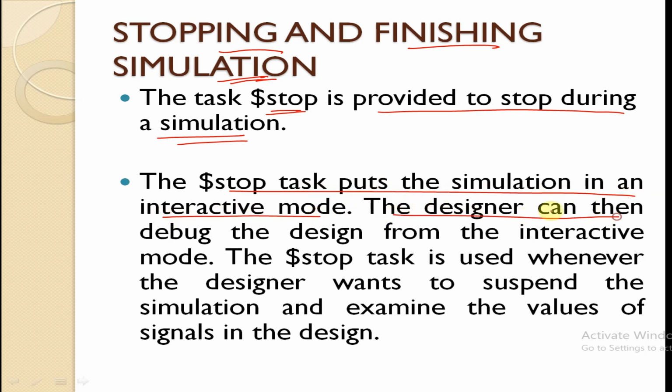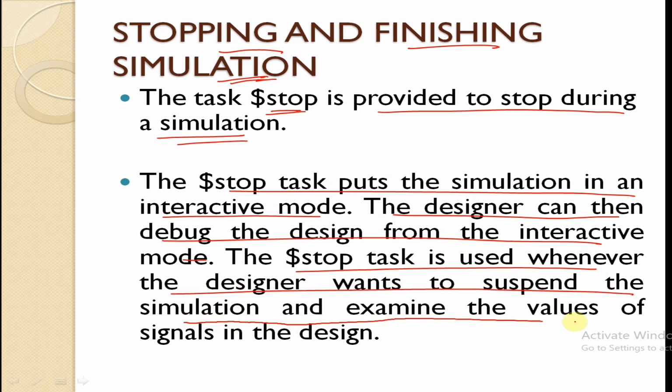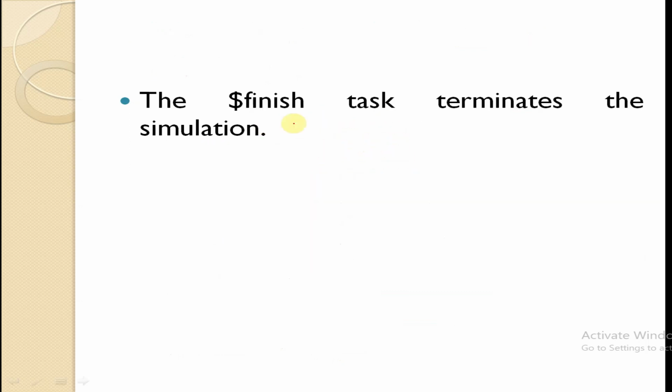The designer can then debug the design from the interactive mode, and the $stop task is used whenever the designer wants to suspend the simulation and examine the values of the signals in the design. So basically this $stop is to stop the simulation and to debug the design. We will see when we are developing a test bench how this $stop is being used in the test bench.